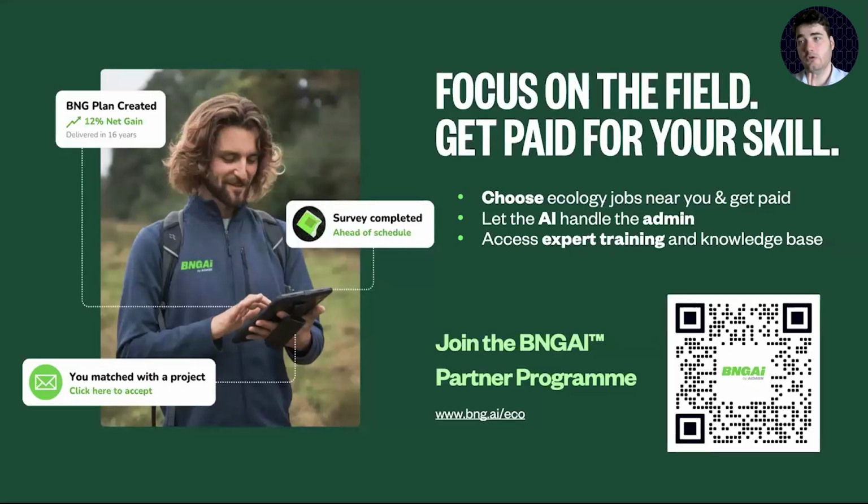So understanding what that bank means, and that's got a specific definition in the RCA. It's not a fluvial, hydrological bank. I'm not a freshwater ecologist, but I am RCA trained, and the bank is really where the bank starts to flatten off, and they say often where you would put a shed. The first point on the bank where you put a shed, and that can be quite high up and far away from where the water actually flows. So understanding that is really important to understanding if a river is off-site and how much land will be in that riparian zone that you need to be very careful about using.